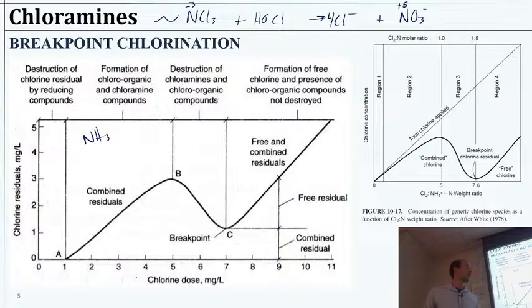Once we finally reach a point where the more chlorine we add, instead of dropping the total chlorine that we observe, because this reaction here would drop the total chlorine, right? This is part of the total chlorine, and this is the total free chlorine that we're adding. So this reaction is getting rid of free chlorine and total chlorine, combined and total, to give us just Cl minus, performing that oxidation.